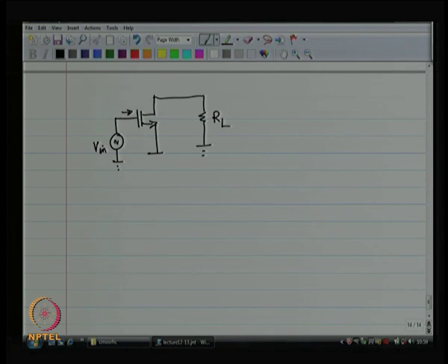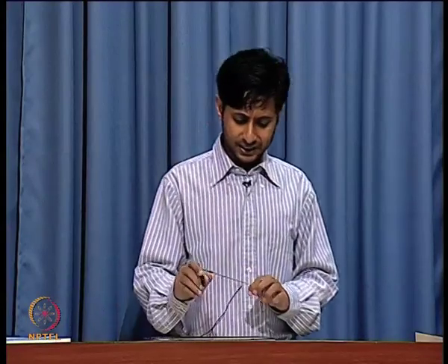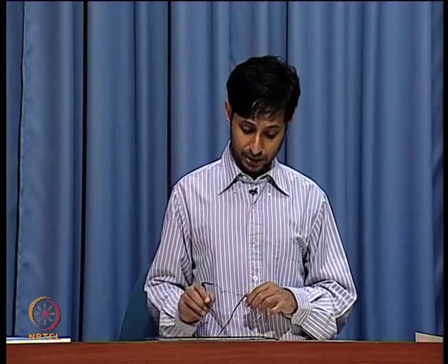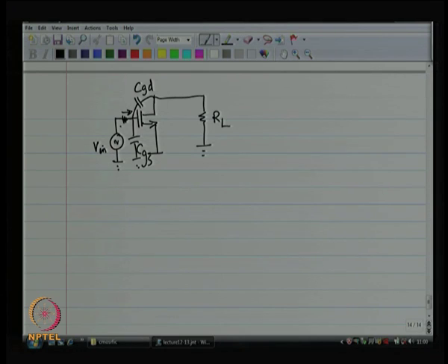Is that current in phase with the voltage? Well, if you only think about CGS and CGD, the current is never going to be in phase with the voltage, right. The gate of the MOSFET is going to look capacitive. So, you have also got to think about the gate resistance RG.